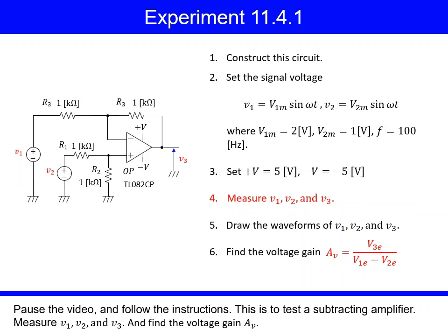Pause the video, and follow the instructions. This is to test a subtracting amplifier. Measure V1, V2, and V3. And find the voltage gain AV.